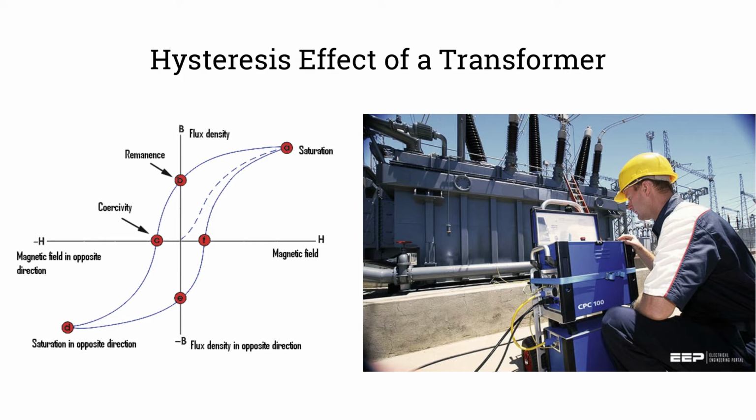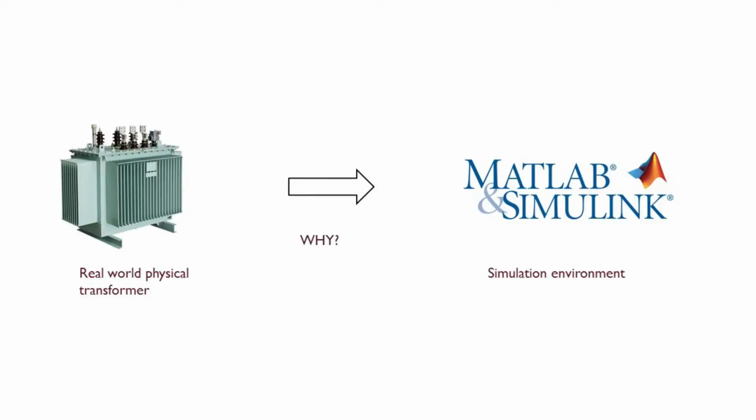Unfortunately, with magnetic hysteresis comes hysteresis loss in a transformer. Every transformer exhibits some hysteresis loss as the input current oscillates back and forth, and these losses manifest as minor distortion and reduced efficiency in the output power. Incorporating magnetic characteristics of the core is important when representing the real-world transformer in a simulation environment. Therefore, we have developed a mathematical magnetic characteristic model to incorporate the magnetic hysteresis effect to the transformer models that are established at present.